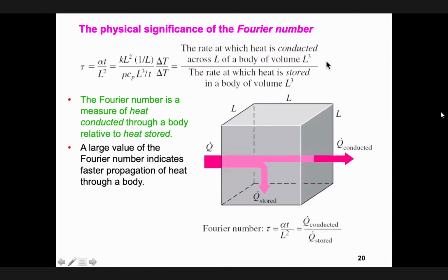If you would like to visualize it, I'm sure you remember this from your building science textbook. There is some conduction coming to the wall. Out of that conduction, all of it will not go through. That's only the case in steady state. But when you consider transient, a portion of that energy will be stored inside the wall. Therefore, this plus this becomes this.